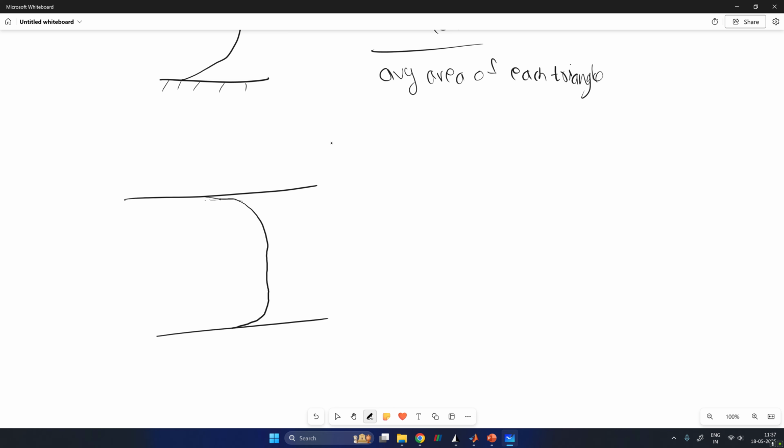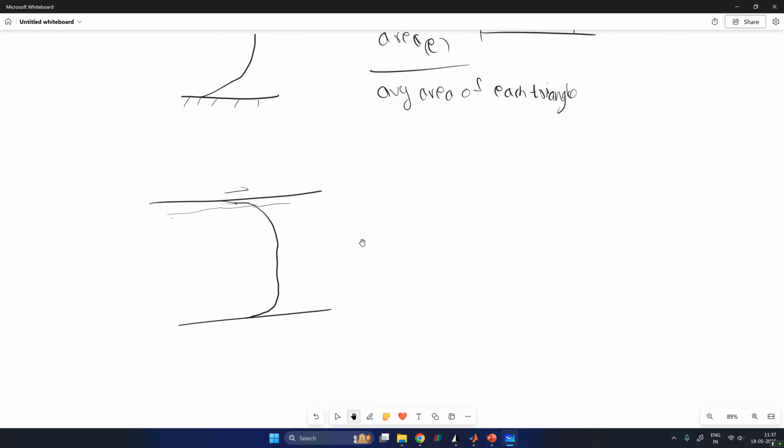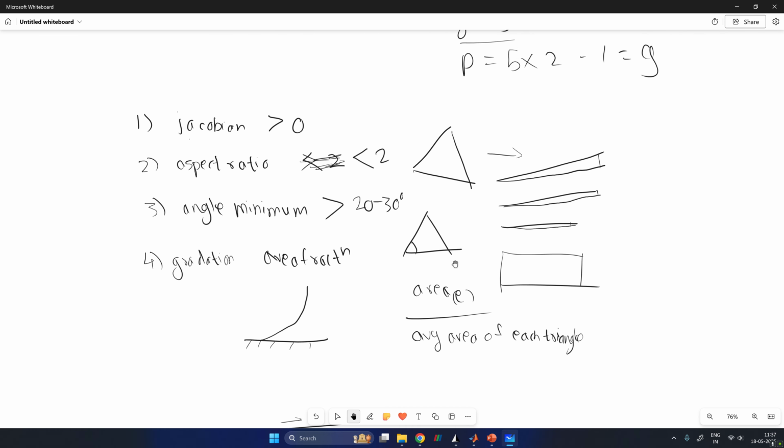We just put a tangential shear stress condition, and we just have to capture the correct tangential shear stress at the wall. And for this you require really correct meshing, and so in that case meshing will have even added importance. So really this depends on the problem, and for our test case, which is really simple, a diffusion problem, we really need to deal with only these 4 parameters.